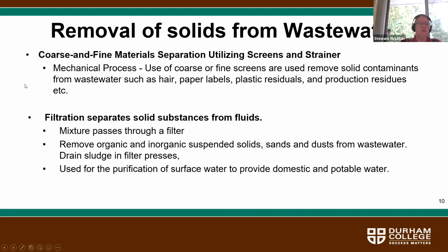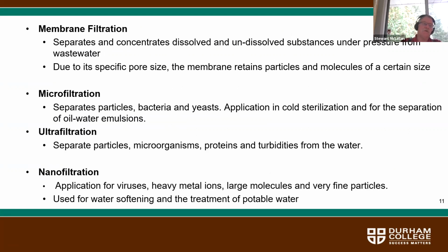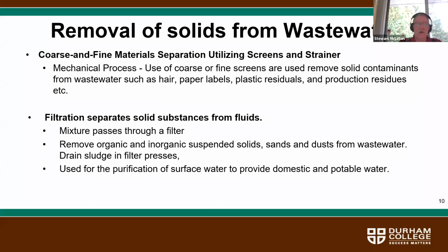Removal of solids from wastewater. Coarse and fine material separation utilizing screens and strainers. So this is further removal of the coarse and fine particle sizes. It's a mechanical process. Coarse or fine screens are used to remove solid contaminants from wastewater, such as hair, paper, labels, plastic residuals, and production residues, etc.